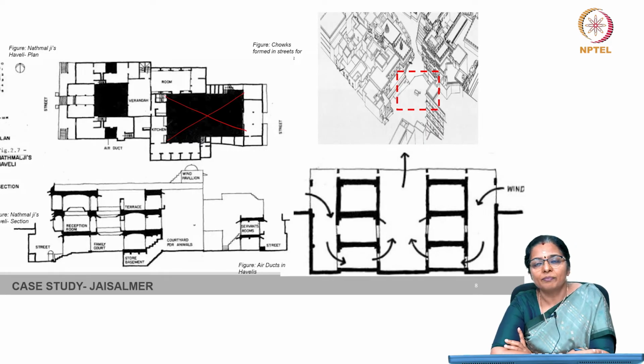In winters, the lower altitude of the sun allows reasonable penetration. Wind gets deflected through the shafts, because there are some shafts too. So, in addition to simple courtyards, very narrow vertical ducts in the form of staircase shafts are strategically used to deflect wind down into the house, thus enhancing natural ventilation and cooling.